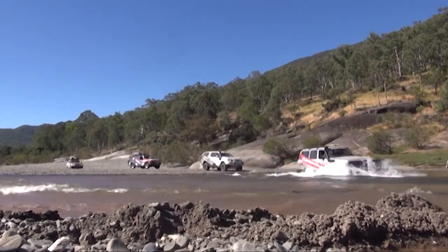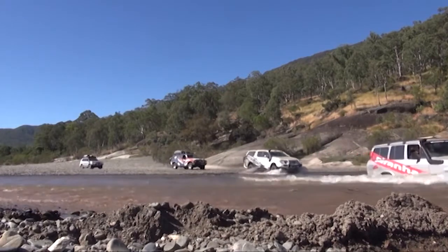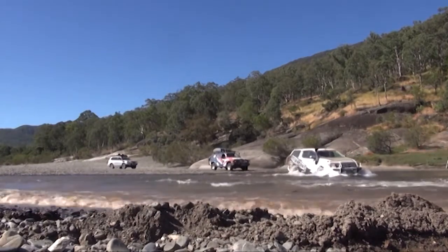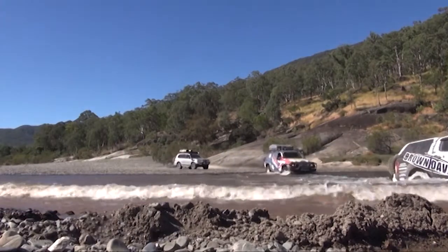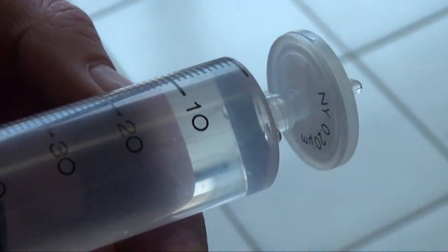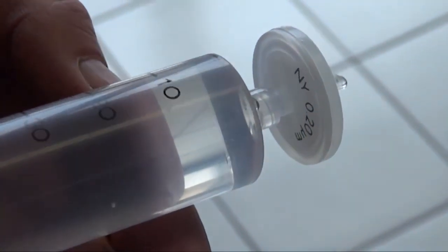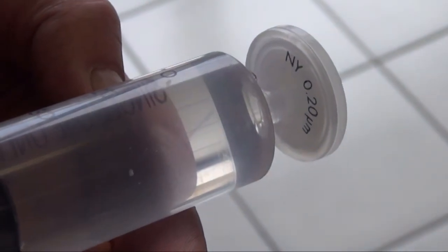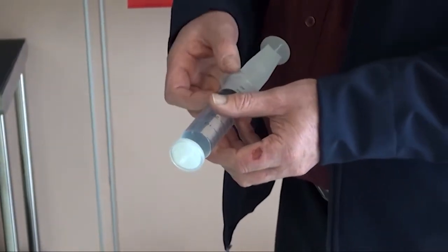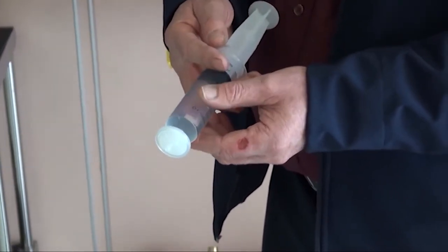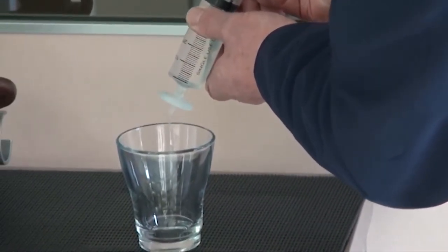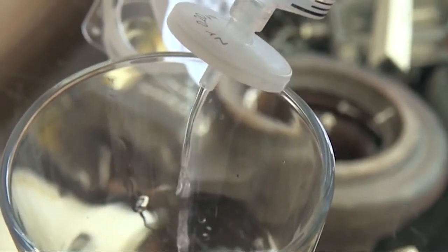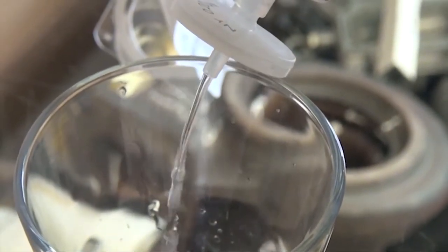The other misconception is that a filter will stop water. Predominantly, a filter is not designed to stop water. It's designed to control particulates. And for the purpose of that exercise, we've got here a 0.2 of a micron filter. 0.2 gives us basically 1/10 the size of the factory filter. And we'll demonstrate that water can easily pass through that filter with very little effort. So as you can see, that a filter in a motor vehicle will definitely pass water. It's not going to be a barrier, water entering the system. A filter is not made to stop water, given that water is a liquid. In fact, water goes through a filter slightly easier than diesel.